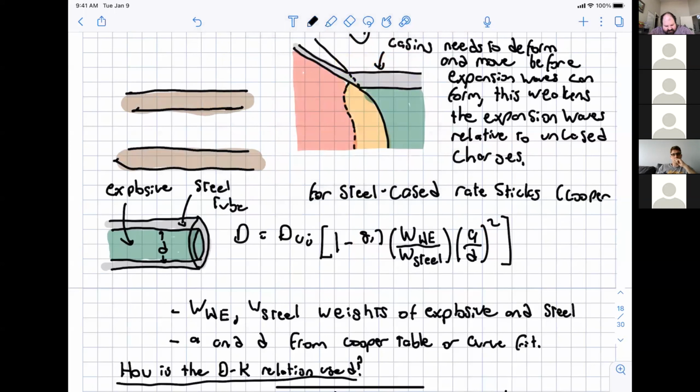So what does that mean? If you have a detonation wave propagating through a high explosive, but the sound speed of the confiner is faster than the detonation wave speed, that means the pressure information from the detonation goes into the casing and actually propagates ahead of the detonation, and that actually reduces the curvature effect. And so there are really interesting gas dynamic or compressible flow effects. The wave structure for that does not look like this. It looks more like this. You'll see a tiny little bit of curvature. The shock will basically jump out in front.